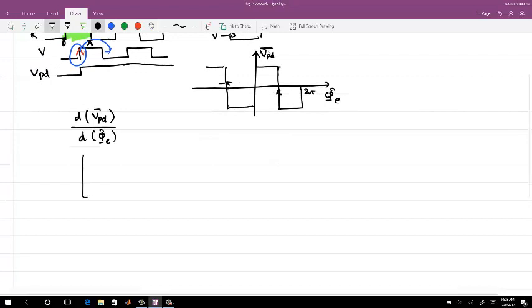So I have this D flip flop, and let's say this is the input R, and here I have a clock, which is V, and this is the output of the phase error detector. If R and V are both square wave signals, then you will see the input output characteristics the way I have plotted.